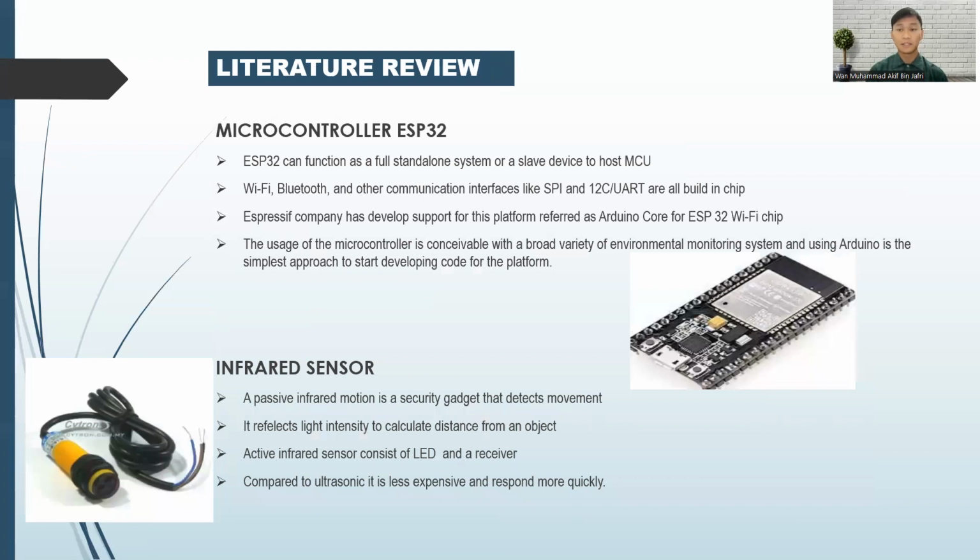Next, for the next literature review, I will explain the ESP32 microcontroller. The ESP32 can function as a full standalone system or a slave device to a host MCU, and it has Wi-Fi, Bluetooth, and other communication interfaces like SPI, all built into the chip. The Espressif company has developed support for this platform, referred to as Arduino Core for the ESP32 Wi-Fi chip. So this makes the ESP32 more portable with Arduino.